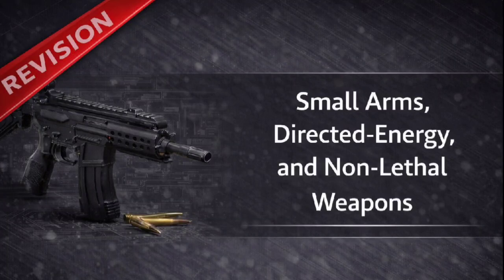Okay, the critical question here is obviously safety. If the breech is unlocked, what stops the case from blowing out the back and injuring the operator when the pressure is at its absolute peak? That is the entire function of the inertia lock. Safety relies solely on the physical inertia of a very heavy breech block mass and the resistance from the return spring. So it's just weight and a spring. That's it. The combined mass has to be sufficient to hold that breech closed for a critical millisecond, just until the propellant gas pressure drops to a safe level. And then it can move back. Then it can move back safely.